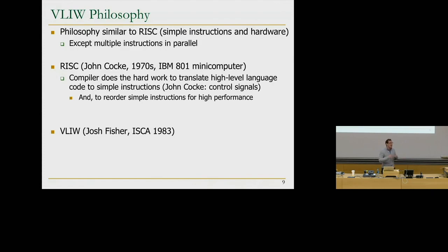You can think of, actually, what are control signals? Control signals are actually micro instructions, right? When we talked about the micro-coded machines, we said micro instruction is really all of the control signals in the machine. So there are instructions at some level, except it's a very low level. So you can reorder all of these micro instructions for high performance. As a result, hardware does little. Hardware is extremely simple in this case. It doesn't do decoding, it doesn't do translation, it's all the software's job to do that.